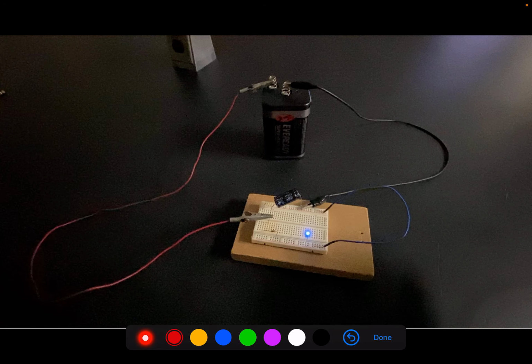I'd now like you to sketch out, not quite yet, the process of discharging our capacitor. So we start with a battery in our circuit, and then we're going to remove the battery and start the discharge process. This is the circuit I'd like you to draw. Show the charges on the different plates of your capacitor, show the direction of current flow, and describe how the current is dropping, the charge on the capacitor is dropping, the voltage on the capacitor is dropping, and the voltage on the resistor are all dropping as time goes on.